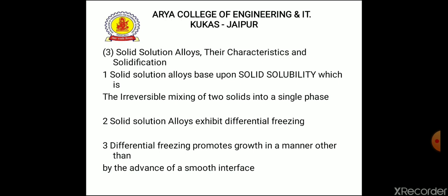The third one is solid solution alloys, which includes their characteristics and solidification. The first is solid solution alloy based upon solid solubility, which is the irreversible mixing of two solids into a single phase. Second is solid solution alloys exhibit differential freezing. Third one is differential freezing promotes growth in a manner other than by the advance of a smooth interface.